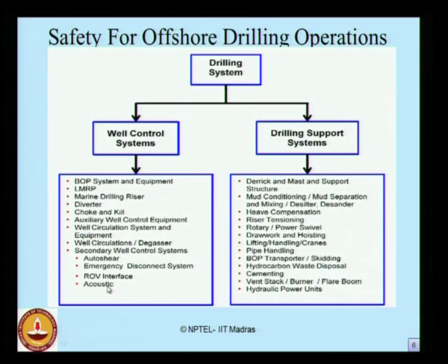interface and acoustic level. If you look at the drill support systems, this consists of the derrick and mast and a supporting structure, the mud conditioning and mud separators, heave compensation devices, riser tensioning systems, rotary power swivels, drawworks and hoisting equipment, lifting and cranes used for handling, pipe handling equipment, BOP transporters, BOP skidders, hydrocarbon waste disposal systems, cementing equipment, vent stack, flare boom, burners and hydraulic power units.